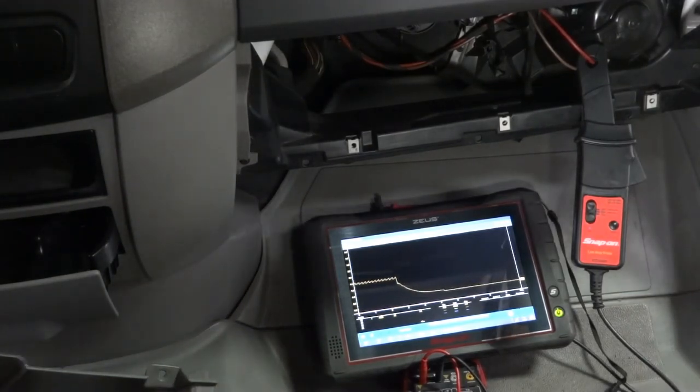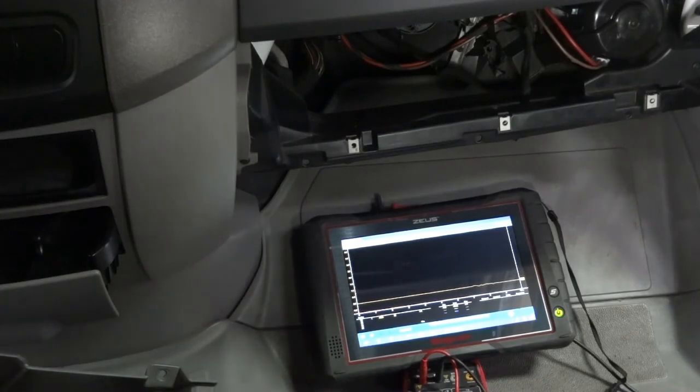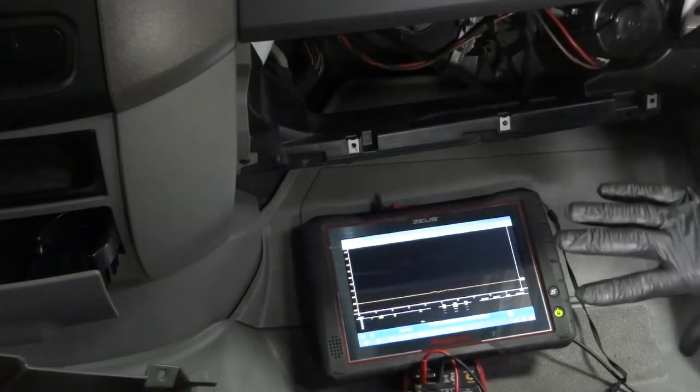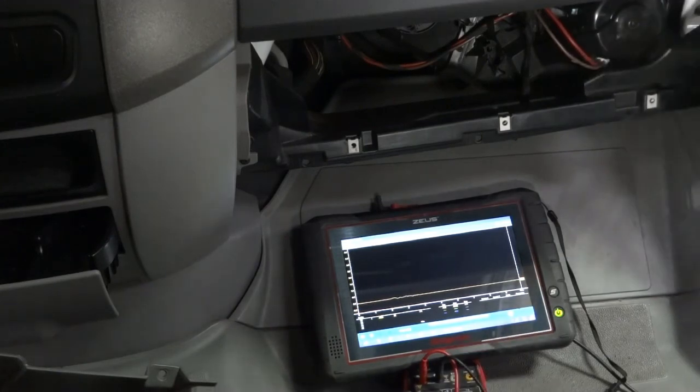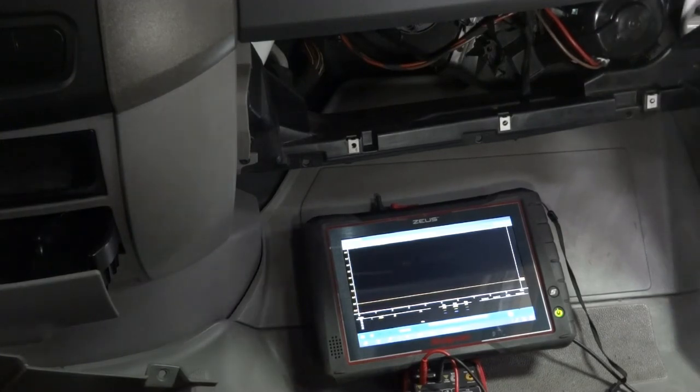Alright guys, so I am going to end this video right here at this point. I am gonna remove this amp clamp and put the cover back on, and then the glove box, and putting everything back together is just a reverse process of the removal process. Okay, I don't think I'm gonna film putting everything back together. It's pretty easy, and I'm sure once I take it for a test drive, the AC is gonna work and everything is just gonna be fine. The problem wasn't the AC, the problem was just the blower motor. Alright, so I'm gonna leave it right here.